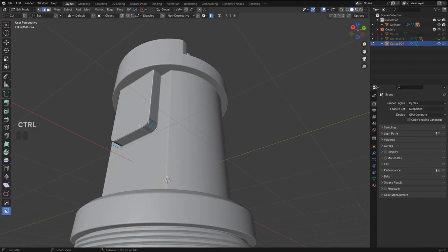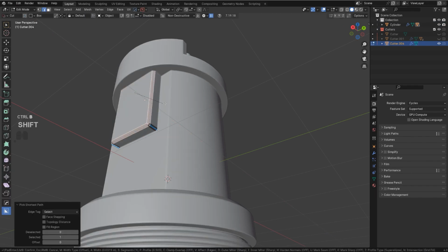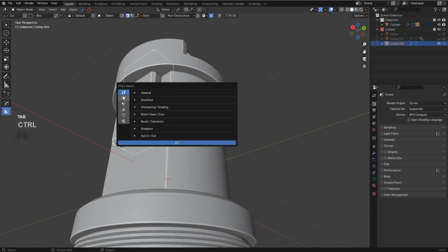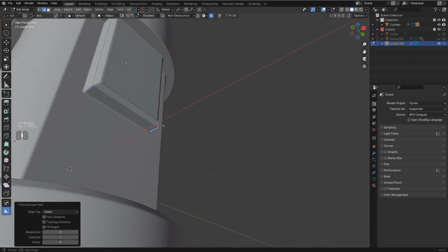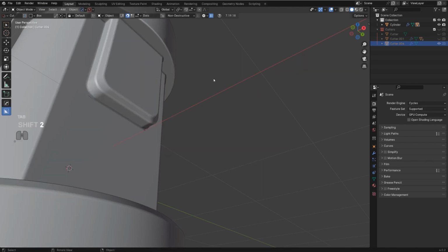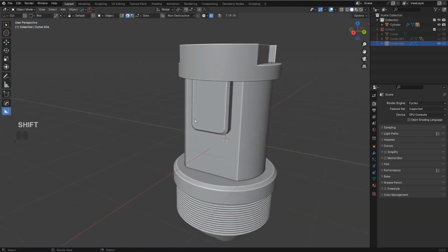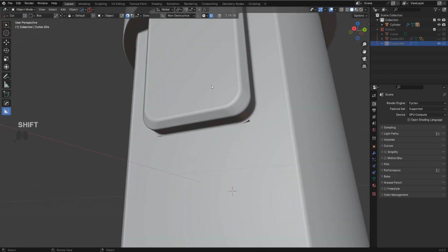And also, let's run the chamfer. Now, when you run the chamfer, you're going to remove a bevel, which is a little bit problematic. So let's nuke this, and then we're going to run the bevel manually on this cutter, like this. And that's good enough. Cool. And then we can actually slice the opening here.